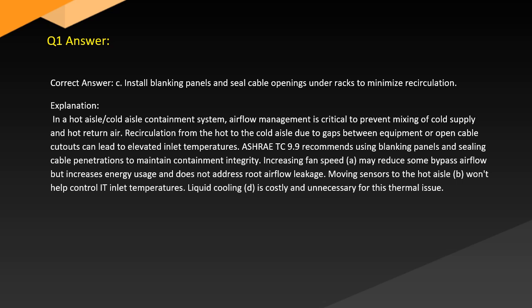Increasing fan speed (A) may reduce some bypass airflow but increases energy usage and does not address the root airflow leakage. Moving sensors to the hot aisle (B) won't help control inlet temperatures. Liquid cooling (D) is costly and unnecessary for this thermal issue.